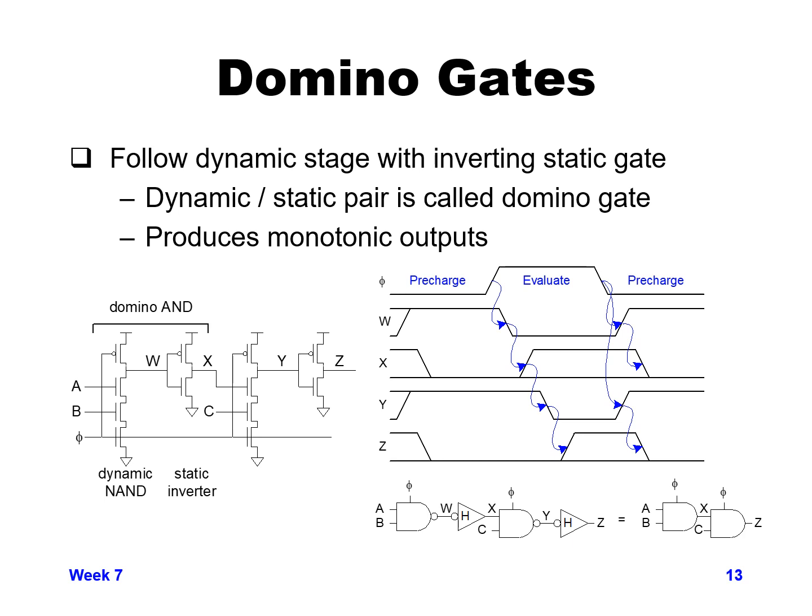And then, of course, we need to make sure to capture that value in a latch or some other state element, because when the clock goes back from evaluate high to a low value, it will precharge both dominoes, so both W and Y will go back to a 1 value, and X and Z will go back to 0 values.